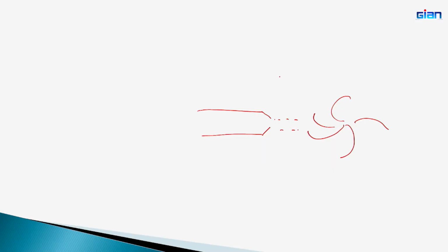Therefore, I must draw this and show you. Now, you can see, water jet comes and you have the needle valve, right. The water jet comes and hits the Pelton wheel or whatever, right. And now this overspeeds and tries to destroy the machines. Therefore, we have a big steel piece here hanging, right, which can immediately drop on this and divert the flow.